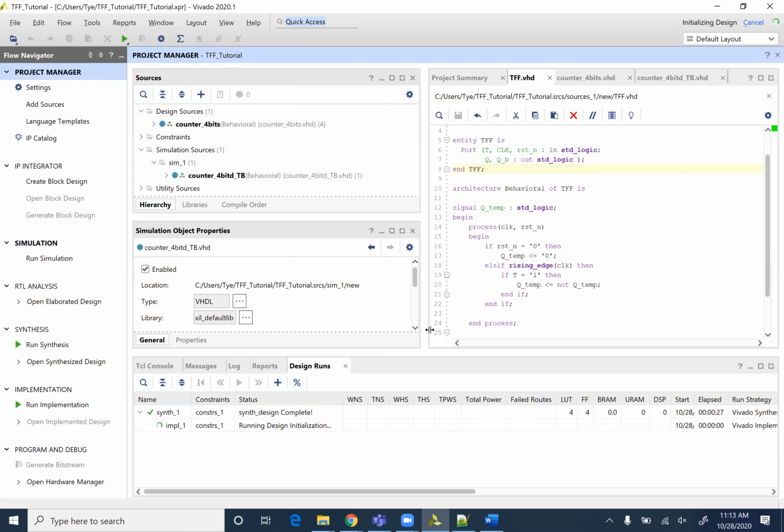So you're saying if you generate bitstream and your board doesn't work right, and then you go back and edit your code, you could generate bitstream again, and there's a possibility that it might not have run synthesis. Yes, but only if you don't click OK to rerunning synthesis, because it will pop up with that little window asking you.